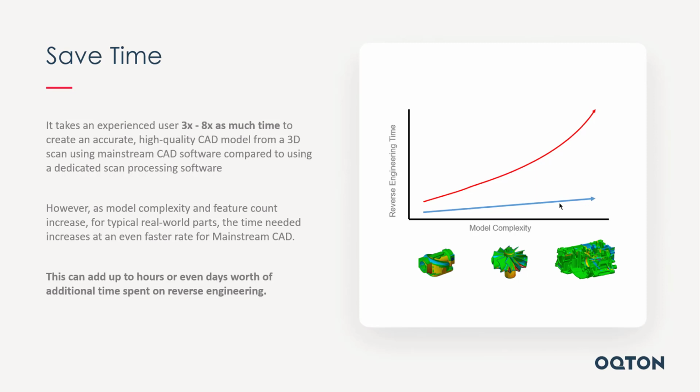That's why I use these 3D color plots on the surface there to show that as I reverse engineer, I can compare back to the original scan and make decisions to understand if I want to make that hole size a 1 inch diameter, and compare it to the scan and see if that's what it really should be or not. You can catch a lot of errors. You can make a lot of decisions along the way that save so much time within the reverse engineering or design process. So as you move up that scale, you're going to save more time.